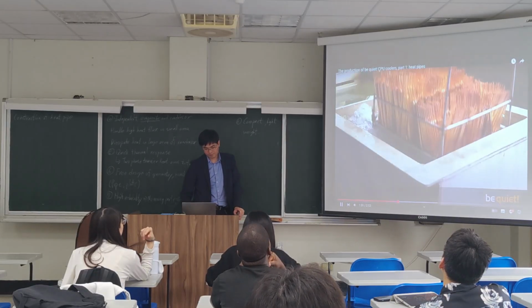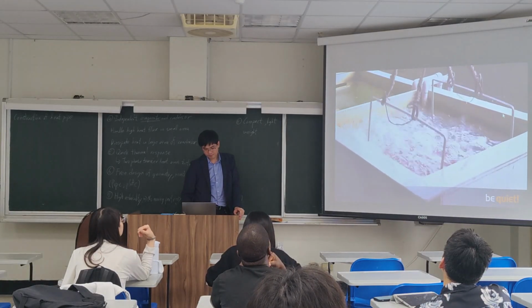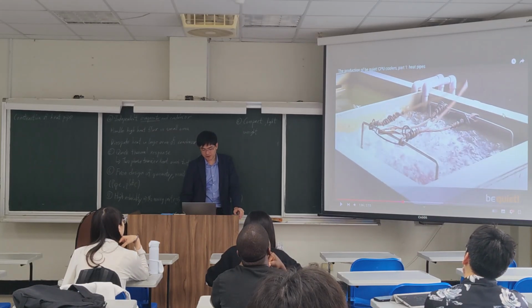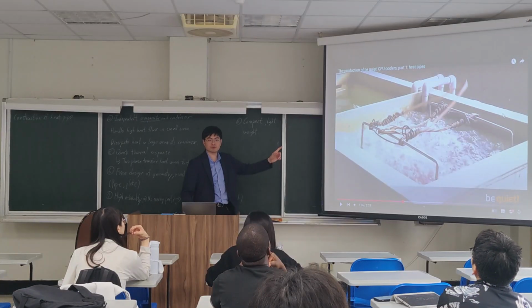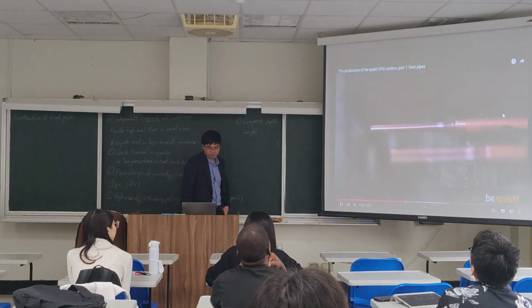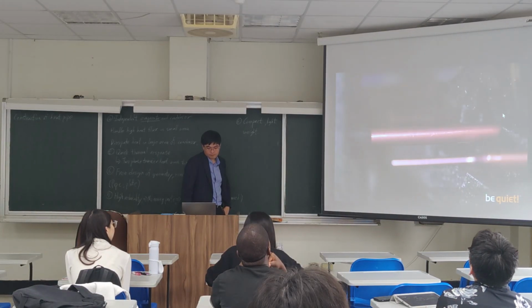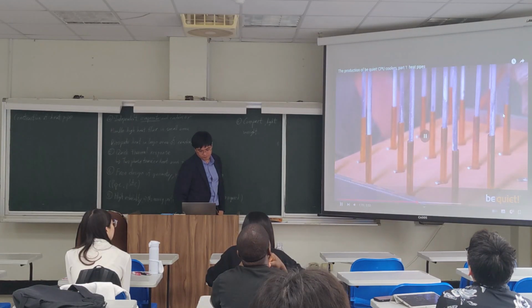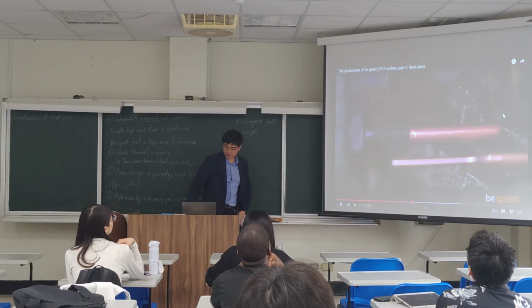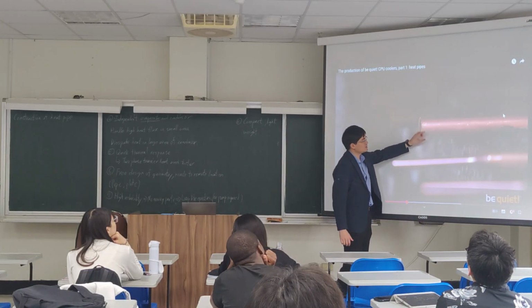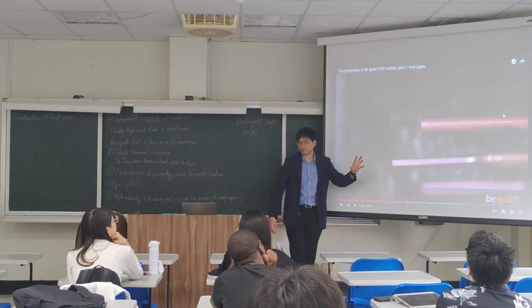Heat pipes are next cleaned in a special cleaning solvent with the help of ultrasound, the ultrasound cleaning process for all the copper pipes. Up till now, it is still just a copper pipe. In the next stage, one end of the heat pipe is compacted and pressed into a taper. The small hole on one side permits its later filling with the liquid coolant. In this process, you can see the copper pipe is pressed from this size to this size, for a later process.